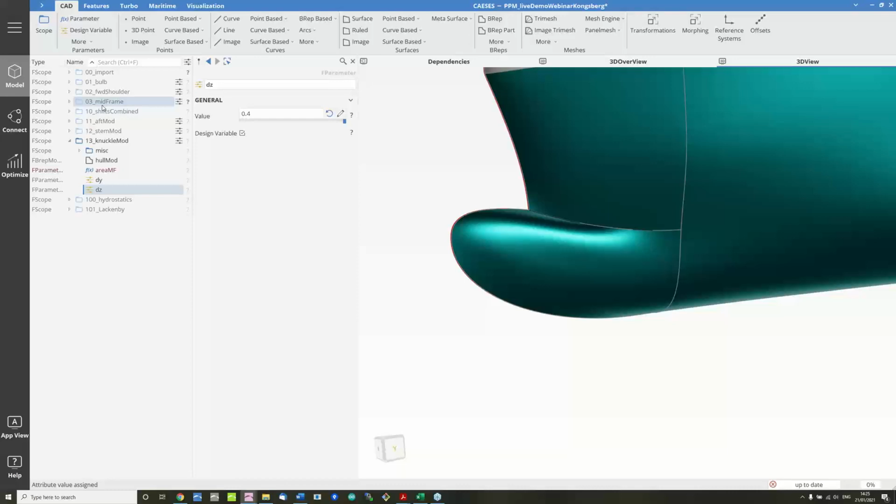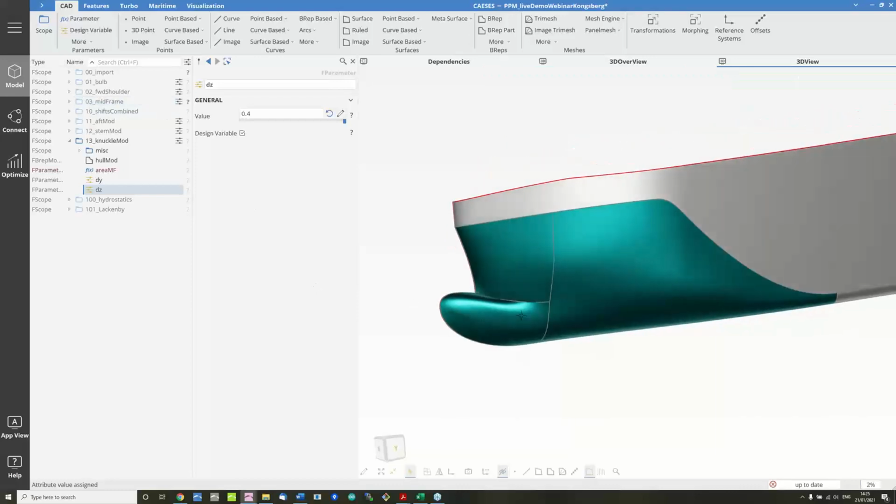What's unique, I guess, to the naval architects amongst our customers is that they are always interested in hydrostatics when they do such kind of modeling. So you would at least want to always know what happens to your hydrostatics while you're doing all those modifications. And as you can see here, I've set up a little feature that allows me to plot certain hydrostatic measures that I've taken from the hull while I do all those modifications. So we can compare maybe what's the mid-frame area of our initial design, or what's the prismatic coefficient. It went down from 0.81 to 0.774 in this case here.